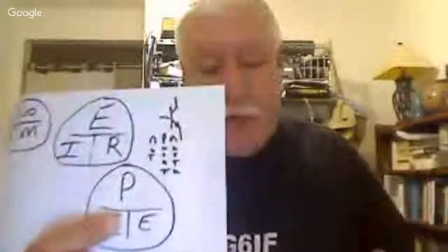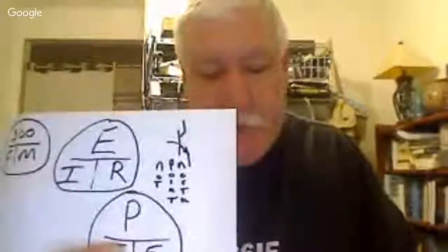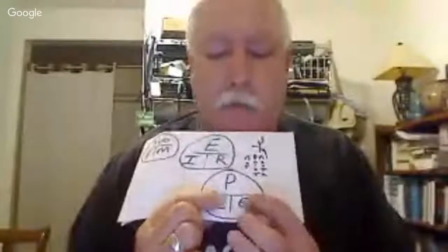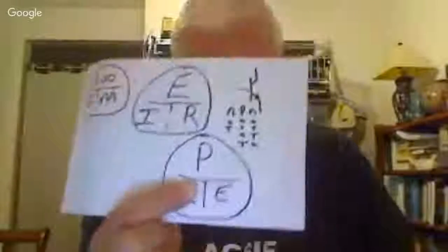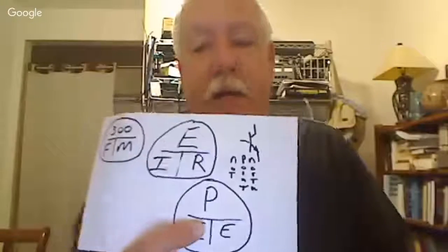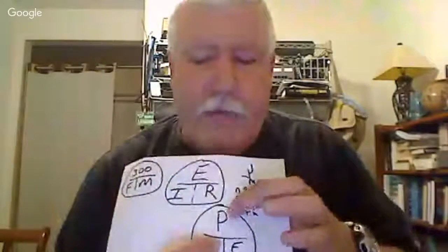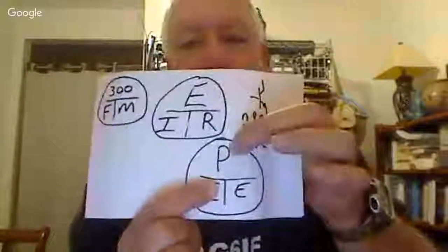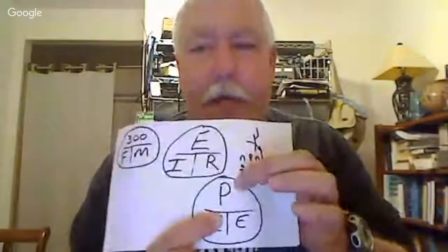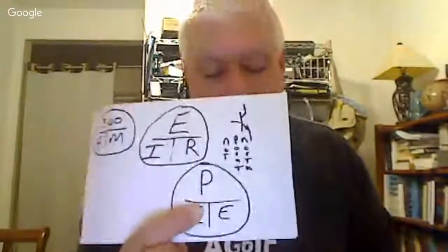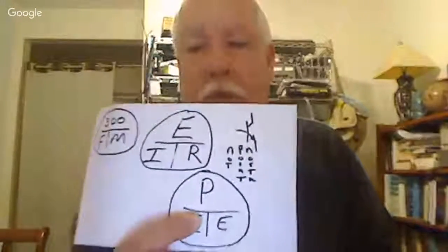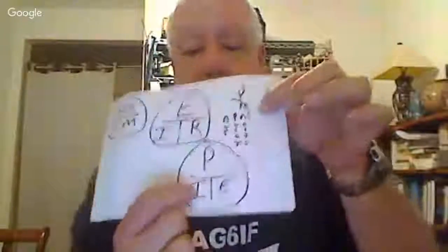So what did they give us? They gave us how many amps flow in the circuit when the applied voltage is 12. So over here we have 12, and the load is 120 watts. So they gave us 12, and they gave us 120 for the P. 12 divided into 120 is 10. And it's 10 amperes because we're solving for amperes.